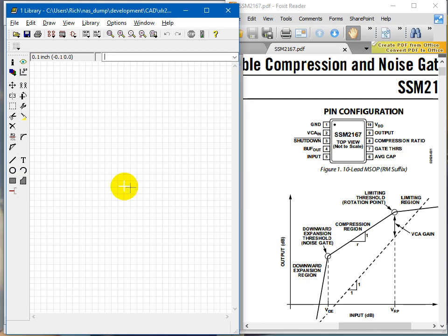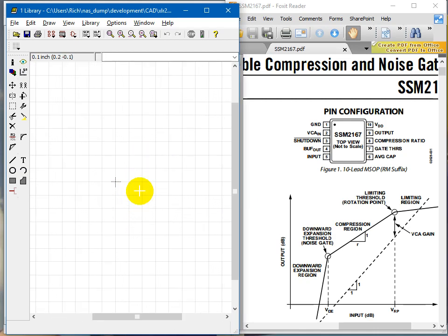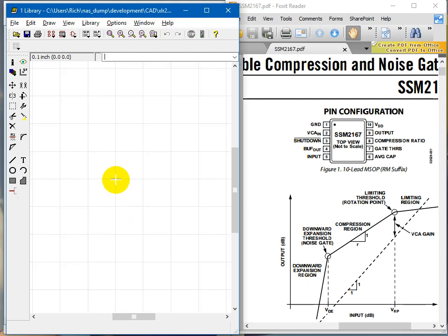Alright, so here's my schematic symbol. We didn't talk much about it in the last segment, but the origin is usually this little dot here, although you can have a reference or a relative origin that might be floating out in space. So when in doubt, put your mouse over it and see what the coordinates up in the top say. So this is 0, 0. That's good. That will be the insertion point if you've ever worked with blocks in AutoCAD or anything else that has these kind of schematic symbol type of things. This will be the insertion point for that. And so I will almost always put that as the first interesting pin.